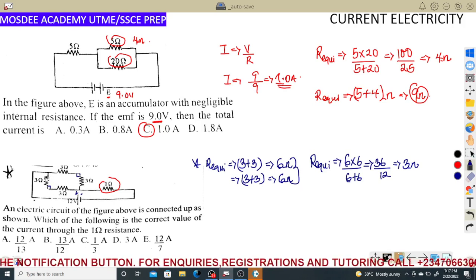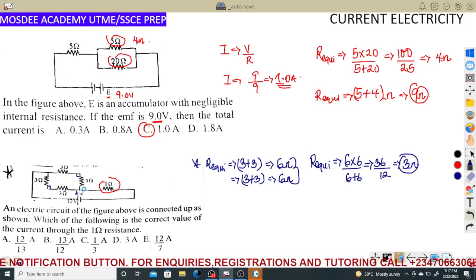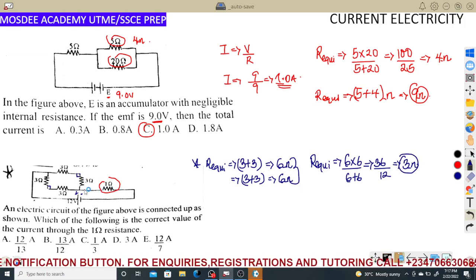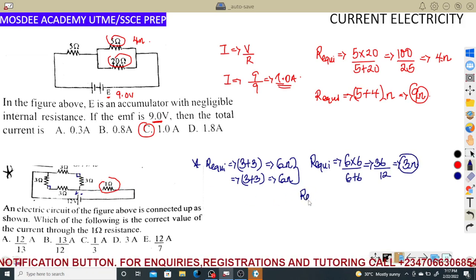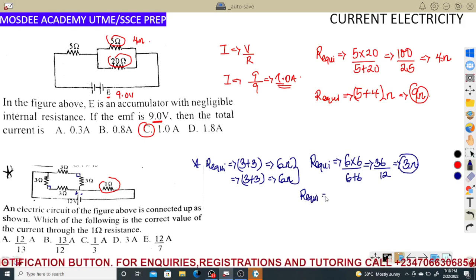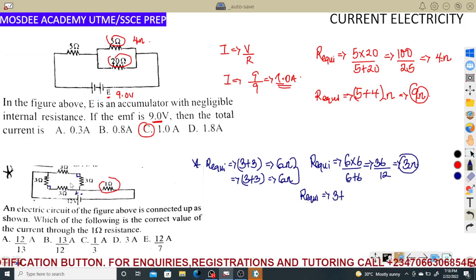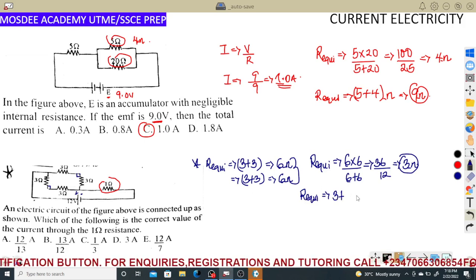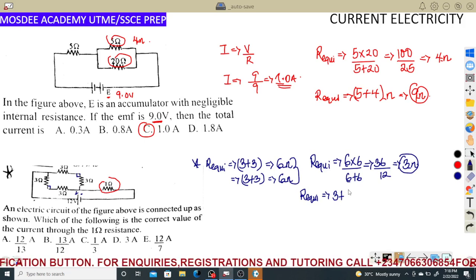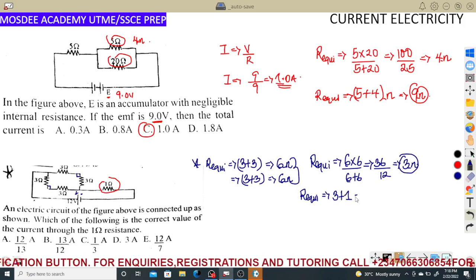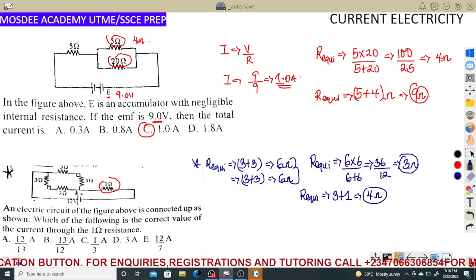So everything in this corner now has been resolved, and the equivalent resistance is 3, which is now connected directly with 1, in series with 1. So you can now say the total R equivalent is now 3 plus the same. Everything is now 3 connected in series with 1. 3 plus 1. Look at the way I'm writing my 1. 3 plus 1 is equals to 4 ohms. So my point is, the equivalent resistance of this box is 4.